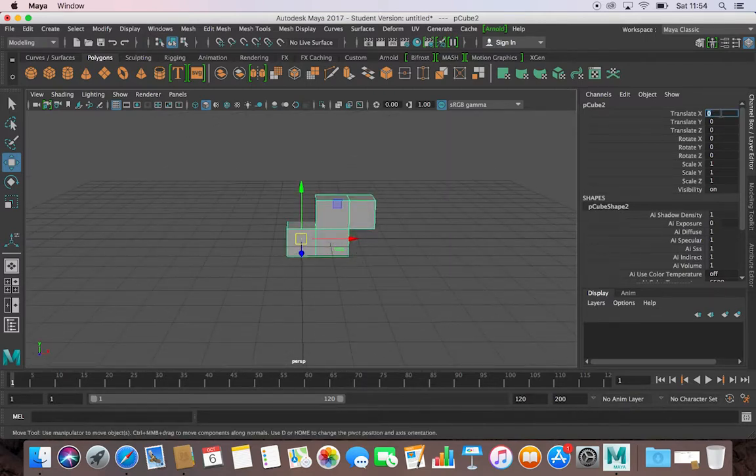We'll type in here -4 and just move our second object there. So this is now where we're going to play with the scaling. If we now change our scale to -1 in the x-axis, if we think of the asymmetry that we have in our x-axis, pointing this way, if we go to -1, it should flip us round so that we have a mirrored object.